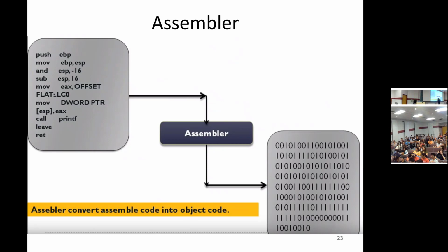Yeah, exactly. And what defines these kinds of patterns or fields? We said this in that Tuesday lecture, right? That's your ISA contract. Thank you. So basically, it's the contract between the software and the hardware that keeps this whole story intact, right? The processor sees only zeros and ones, but it is implementing a certain ISA that says, well, 0, 1, 0, 1, 0 is a sub operation. So you should pass it to your ALU, which does the subtraction. Your second field is your first register or first value that you should subtract, the next one is the second value, etc. Right? Does this make sense?